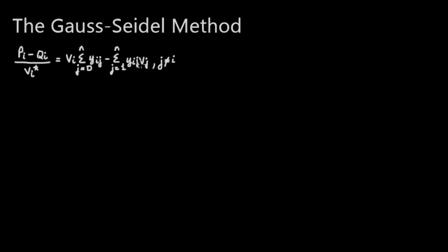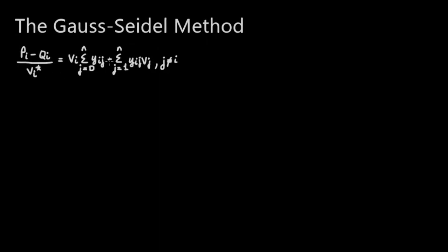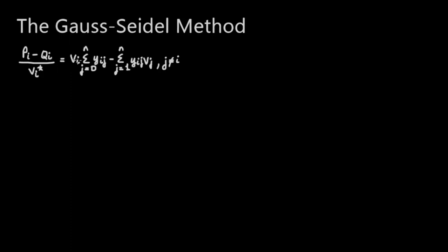And so we can use this power flow equation and combine that with what's called the Gauss-Seidel method to solve this set of nonlinear equations. Let's see how we can do that. In the Gauss-Seidel method specifically, we're going to be solving for the voltage in one way of using this equation, and we can also solve for the real power using this equation as well, and the reactive power using this equation as well. Alright, so first we're going to solve for Vi